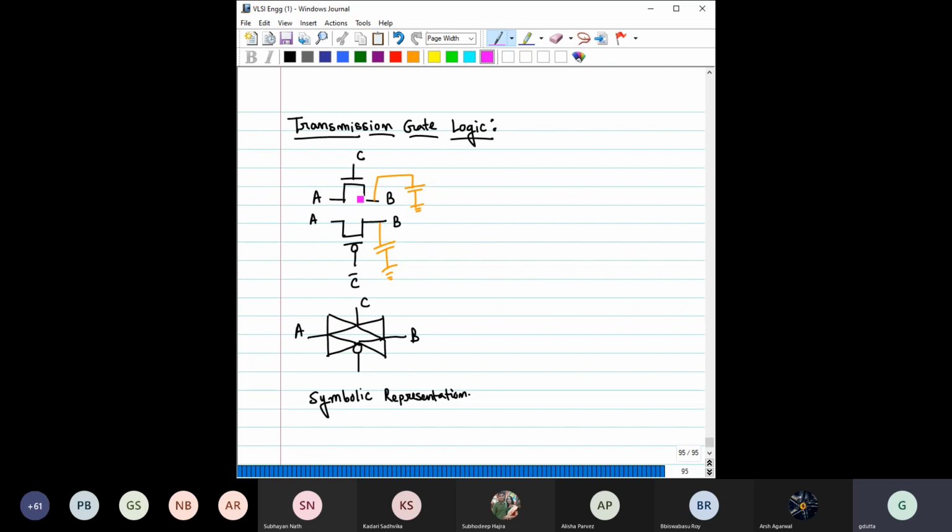So for example, if we are designing this using pass transistor logic using NMOS, and suppose you are charging it from 0 to 1, then you make A1, make C1, right? So that gives a connection and it will start charging, but you cannot really go to 1, meaning VDD. You can reach only up to VDD minus VTH.